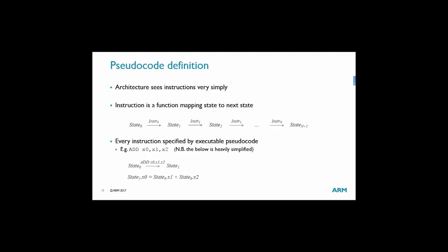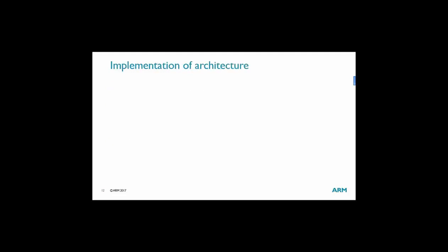So it's very straightforward. The architecture views all instructions in a simplified way like this. They simply must perform particular pieces of behavior. However, the implementation of our architecture in our processors is much more exciting and not as straightforward as this. As you saw on M7's pipeline earlier, there are many speculative views of the architectural state flying around inside the processor at any given time.